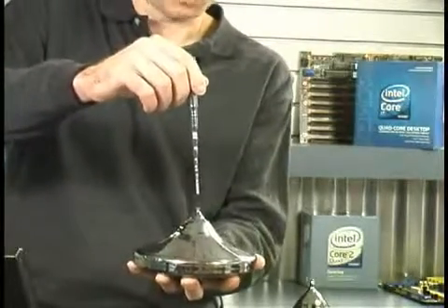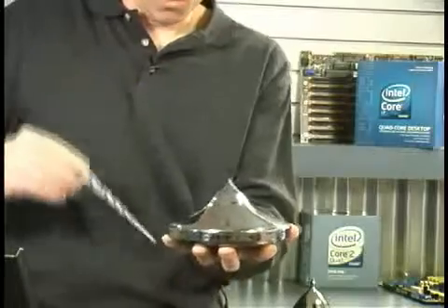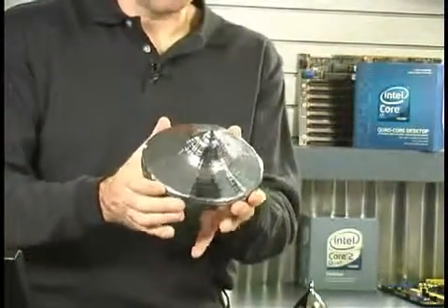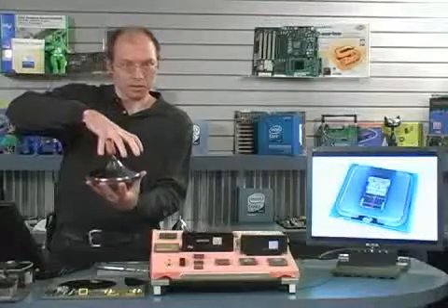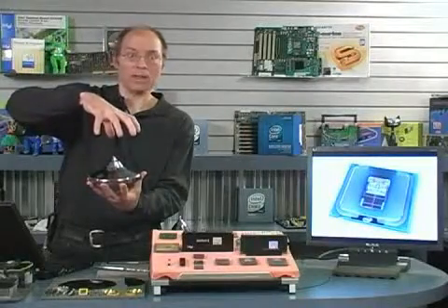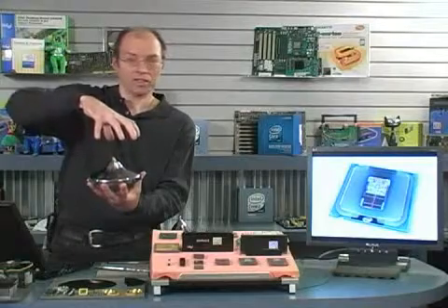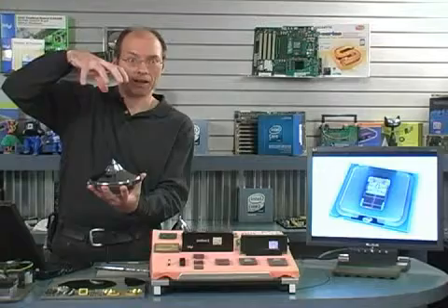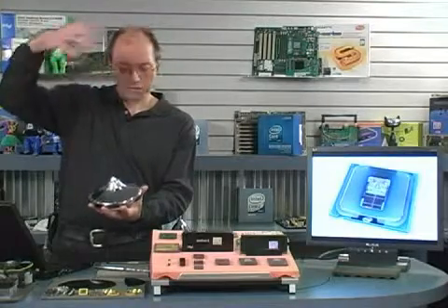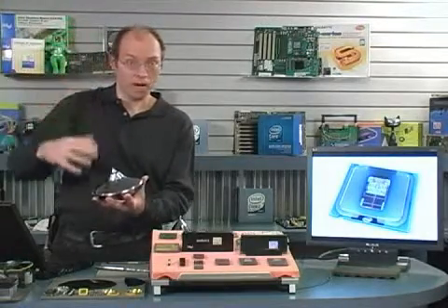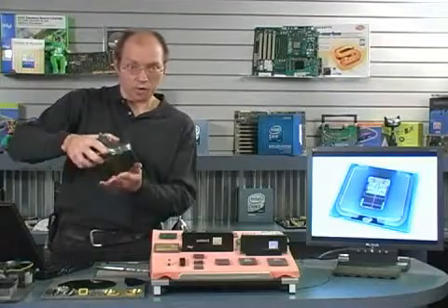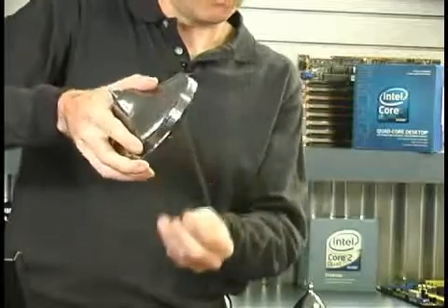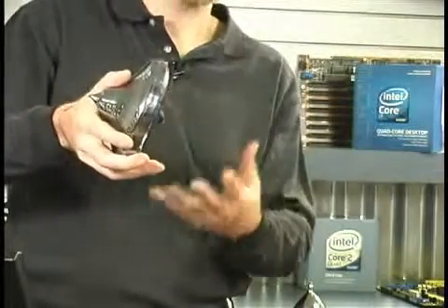This is like millimeters per hour. It's a very slow process. Now, once the crystal reaches the diameter that it is intended to be, then the process speeds up a little bit. It's pulled out a little bit more quickly until basically what we have is like a cylinder. Imagine a cylinder of this crystal material being pulled out of this vat. Once the cylinder has reached its final length, which is usually a couple of feet long, then the pulling process goes more quickly and we end up with a tail. They want to have a gradual pull out of the material from the vat to prevent any kind of thermal shock.